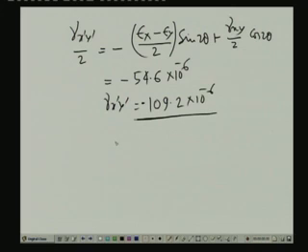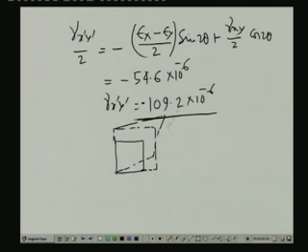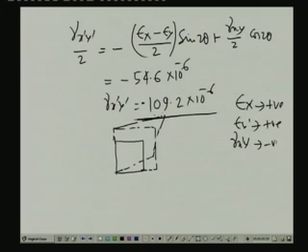So, you see initially we had the element which is in this form, and we had a strain which is positive in the x direction, and a strain which is positive in the y direction. So, this is the positive strain, and then gamma xy also is positive, which means the angle is reducing, which is in this form. So, this is the position of the element, and in this particular case when we are computing the strain at 30 degree, we have epsilon x dashed as positive, epsilon y dashed as positive, and gamma x dashed y dashed as negative, and hence if we plot that, you can get the configuration corresponding to that particular element. Well, we will deal with this in the next class.